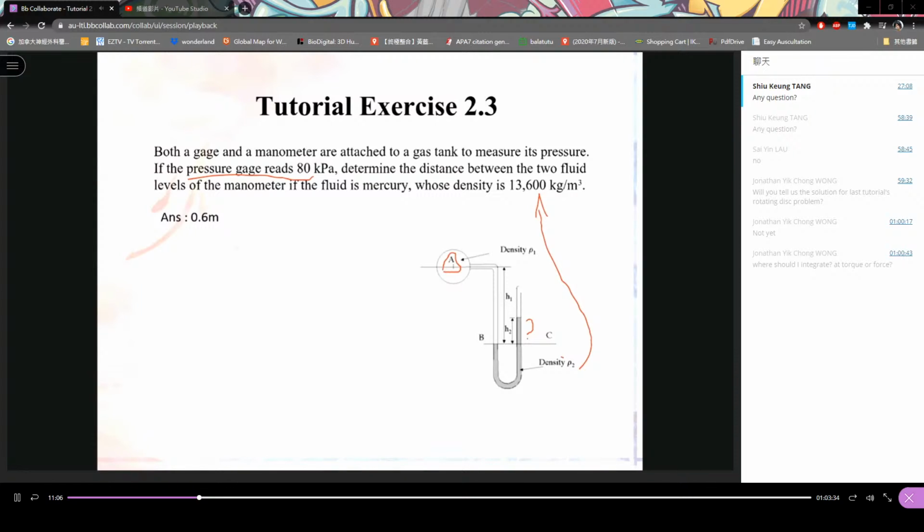Oh, a hydrostatic equation. Well, we need to find somewhere to set up our pressure balance. So usually, because mercury is at rest, it's in equilibrium, so we choose this level, B, C, to set up our pressure balance. This is point C. Because of equilibrium, the pressure at B is equal to the pressure at C. Now remember, the two rims of the U-tube have the same cross-section area, so this pressure is equal to that pressure. Okay.